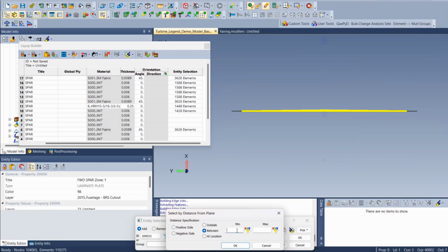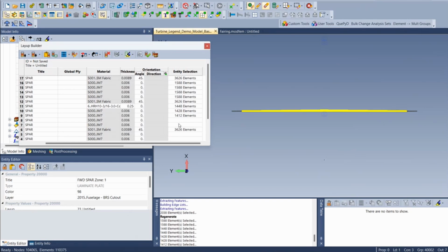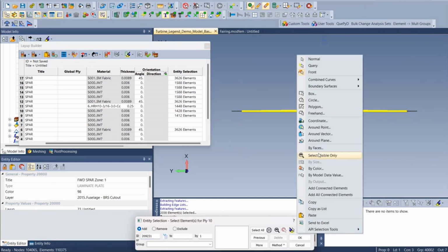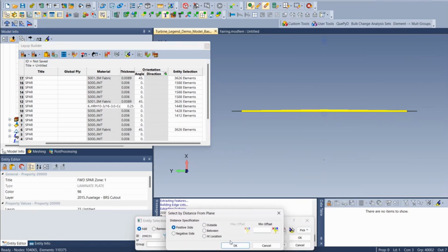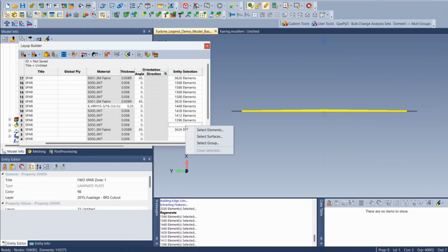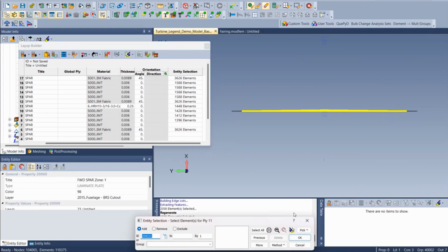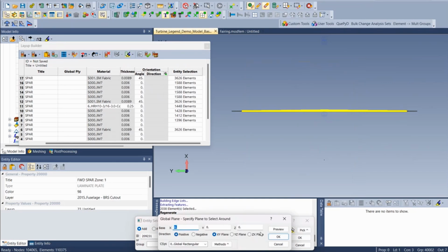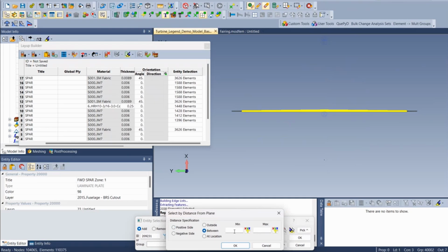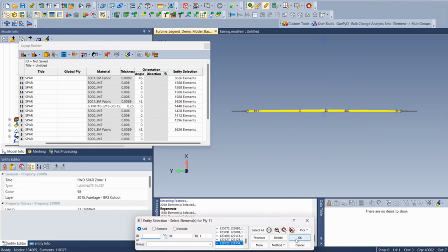So probably guys who've done any layups on aircraft probably know trying to define spar uni patterns across the entire model makes this really difficult. You're doing pick what? I'll show you. Minus 144. Distance plane. Yeah, so pick around plane. Select elements. Pick around plane, using the ZX plane as my reference point, and then defining from that region. There's probably a way we could API this.